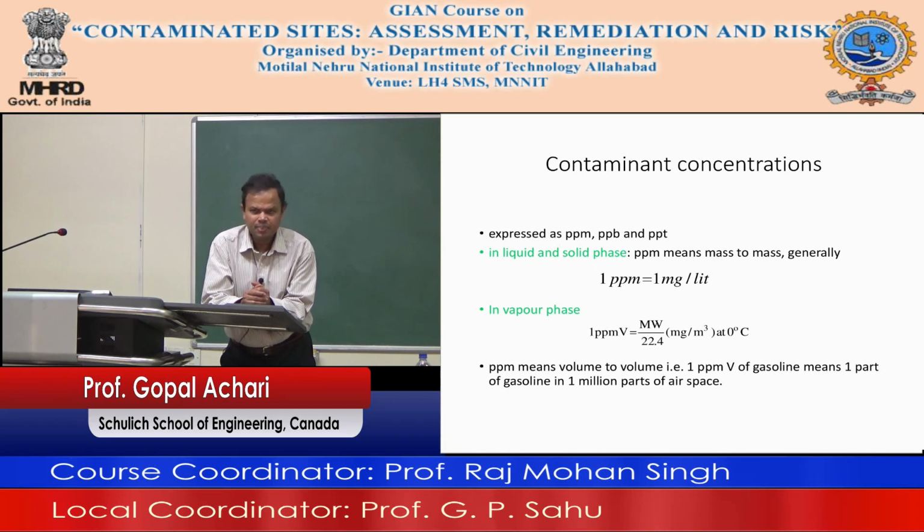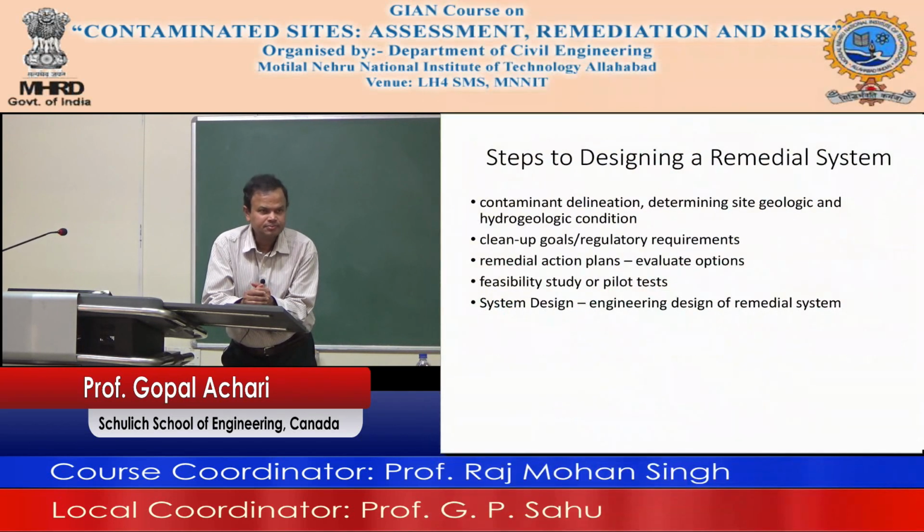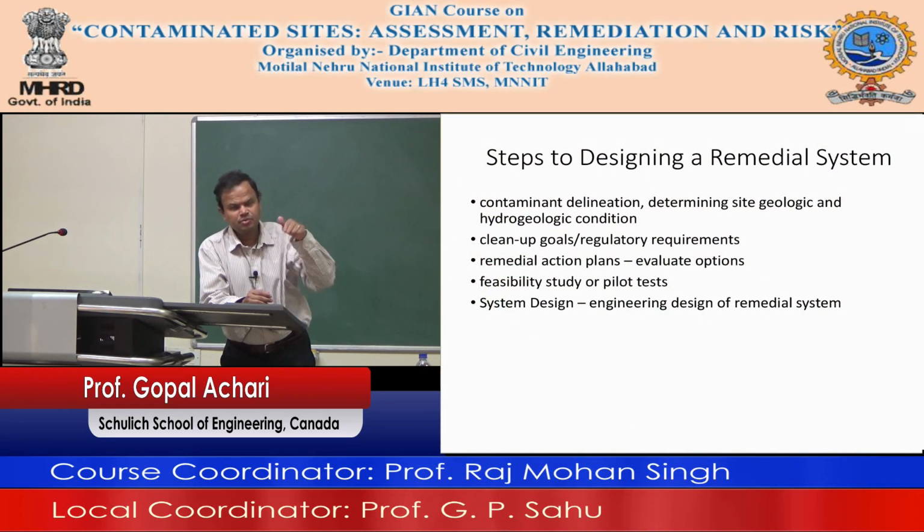What are we talking about here? How far is the groundwater table? What is the geology in the subsurface of the well? Like how deep is the bedrock? Is it a shallow bedrock? Is it a deep bedrock? Is the bedrock fissured? Is the bedrock cracked? Do you think the groundwater is moving at a faster rate in a particular direction?